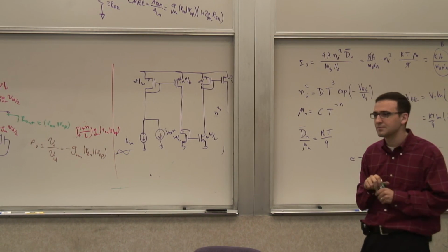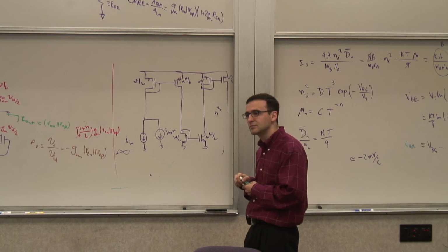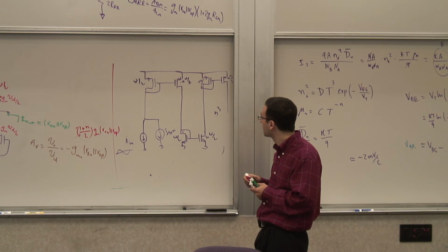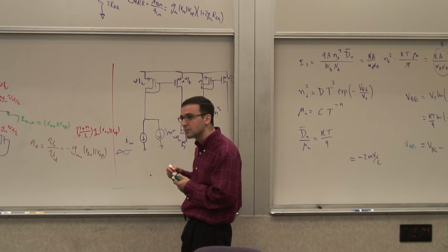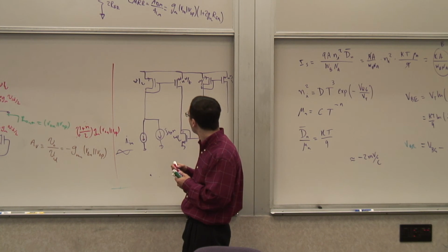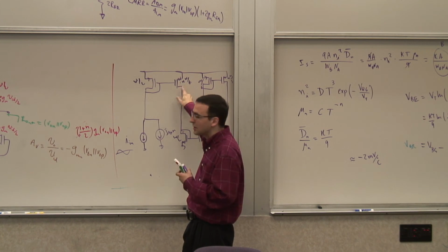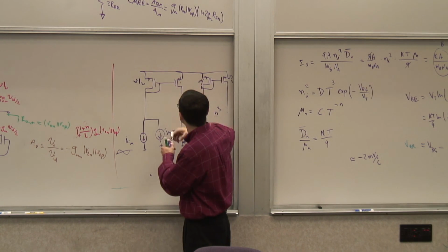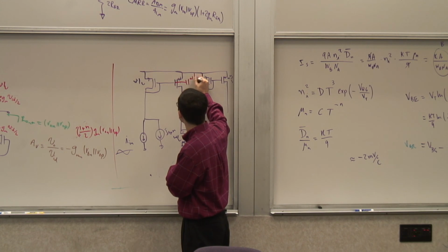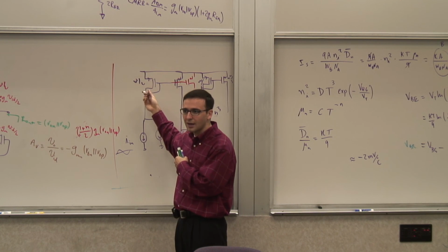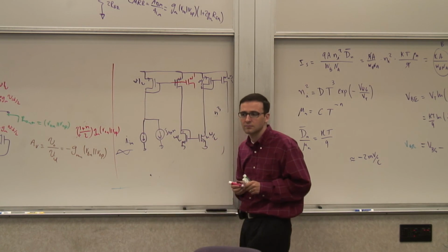Yes. So would stacking transistors have the same effect? Or can you just put transistors, you mean you make them cascodes? No, like put them side by side so they're sharing the same. In parallel? Yeah. Here? Oh yeah, it's the same thing. Because you think about it, right? I could make this out of, let's say, multiple transistors in parallel, right? And all of their gates are shared, all of their sources are shared, so all of their CGSs are in parallel. So it's another way of doing the same thing, exactly.